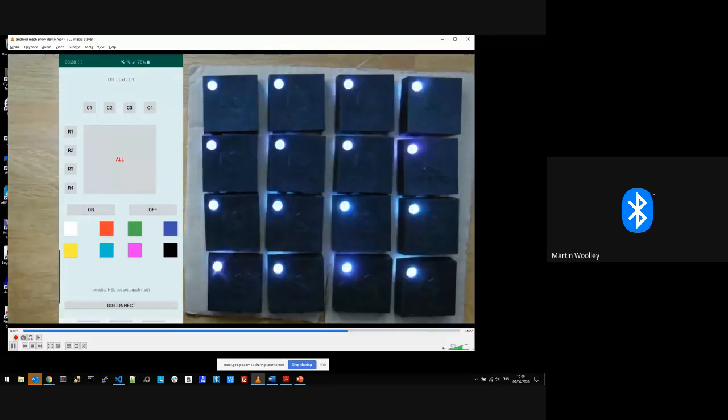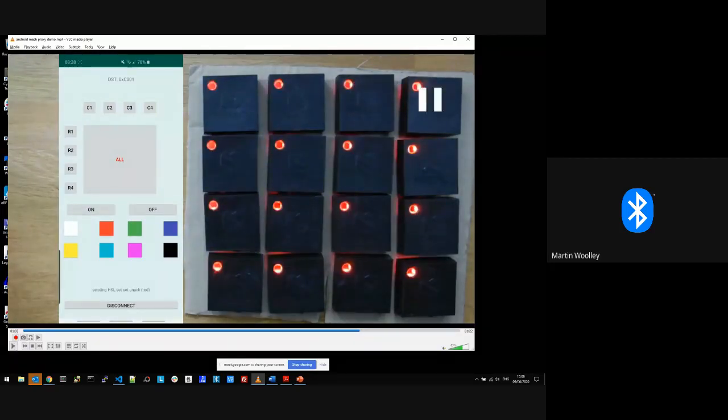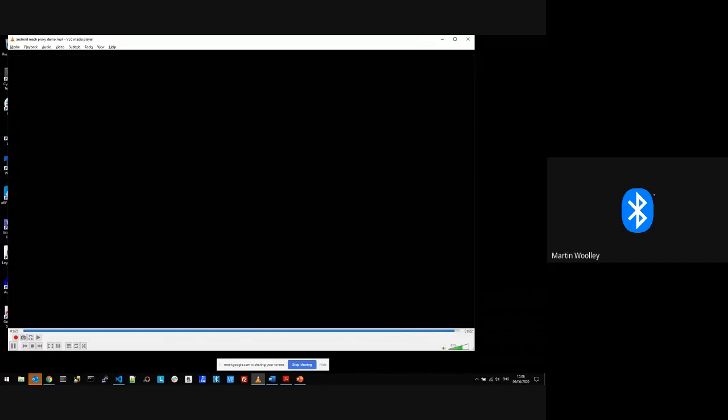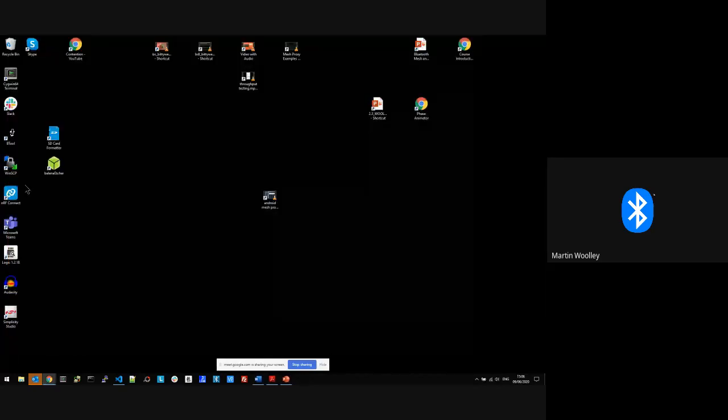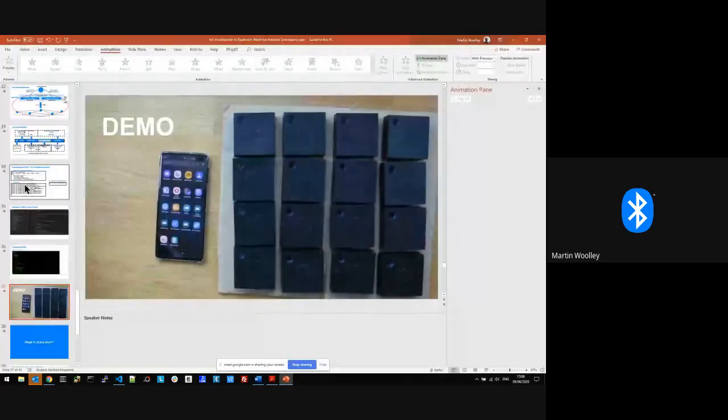Switch them all on again, and I'm going to change the colors now. So I hit the red icon, and that sends a light HSL set unacknowledged message with a set of parameters that selects the color red. And so on. I'm just exercising, selecting different addresses, and sending messages of a given type to those addresses. Those devices that have subscribed to that address and implement the right models are responding, as you can see, all being done by an Android application which is connected to a proxy node, which acts as a kind of go-between.